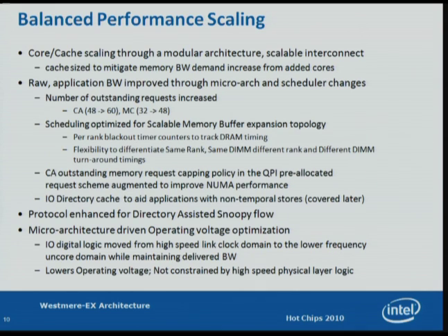Now we have built in, and I'll talk to this in more detail, an IO directory cache to help HPC type applications, some of which have a high percentage of non-temporal stores. And then we have a protocol enhancement that we call a directory assisted snoop flow, which I'll talk to. And then there are some microarchitectural techniques by which we were able to reduce the operating voltage, which improves your power efficiency.